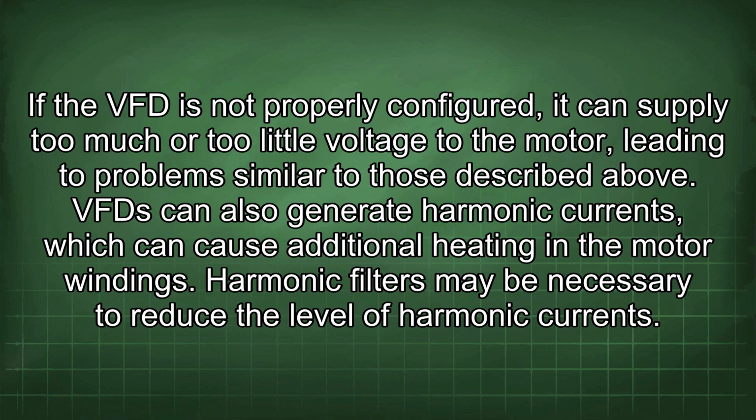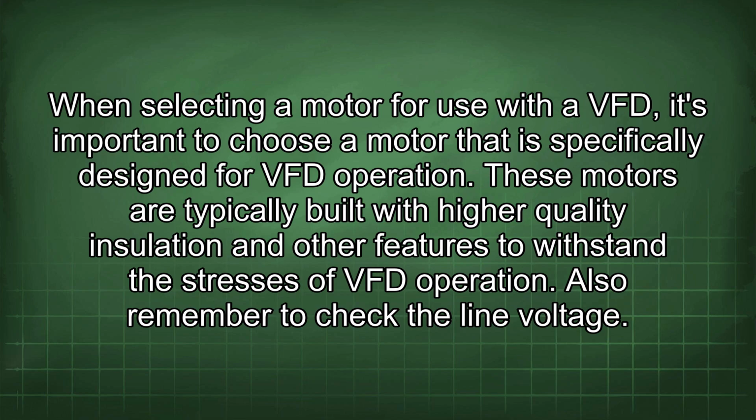VFDs can also generate harmonic currents, which can cause additional heating in the motor windings. Harmonic filters may be necessary to reduce the level of harmonic currents. When selecting a motor for use with a VFD, it's important to choose a motor that is specifically designed for VFD operation. These motors are typically built with higher quality insulation and other features to withstand the stresses of VFD operation.